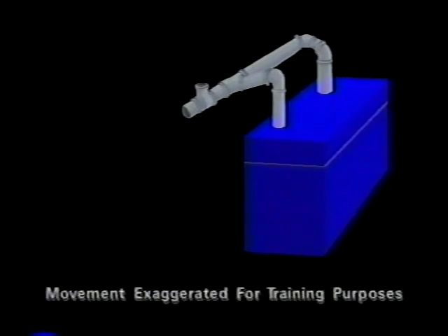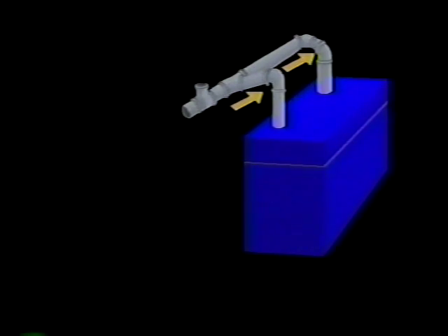When the boiler is steaming, the header will expand more than the boiler. Here, the expansion forces are exerted against the elbow connections to the boiler risers. Swing joints provide protection against cracked and leaking fittings and boiler sections.